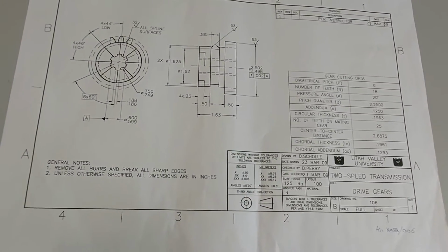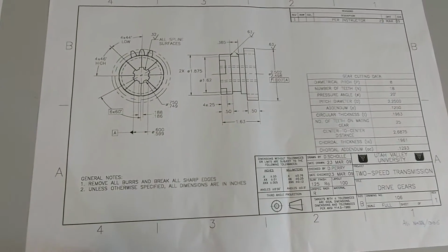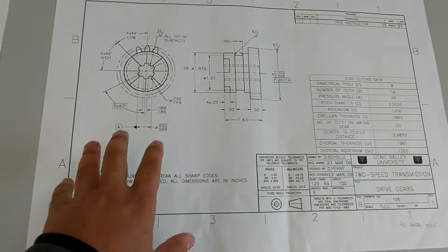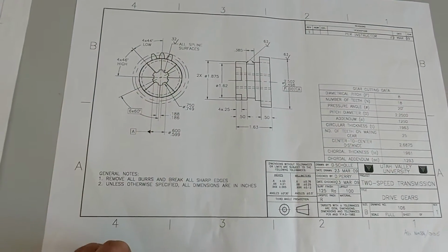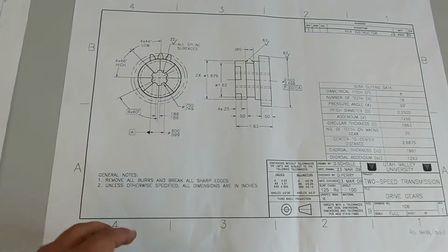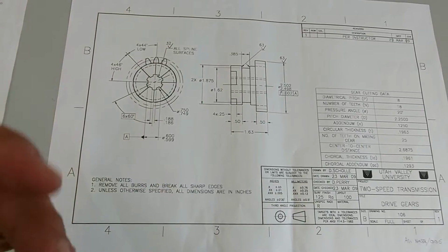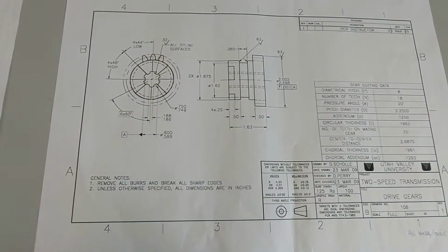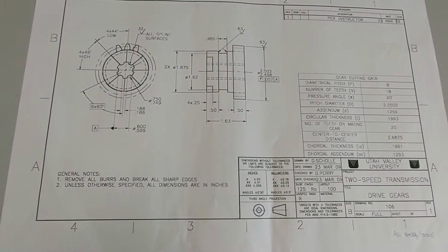It depends on whether the views are communicative enough. For example, if 2 views are enough for the drawing to be communicated to the manufacturer or the technician or the machinist, then use two views. If you need more than 2 views, like 3 views with a top view, for better communication and better understanding of tolerances and details, then you will use 3 views.